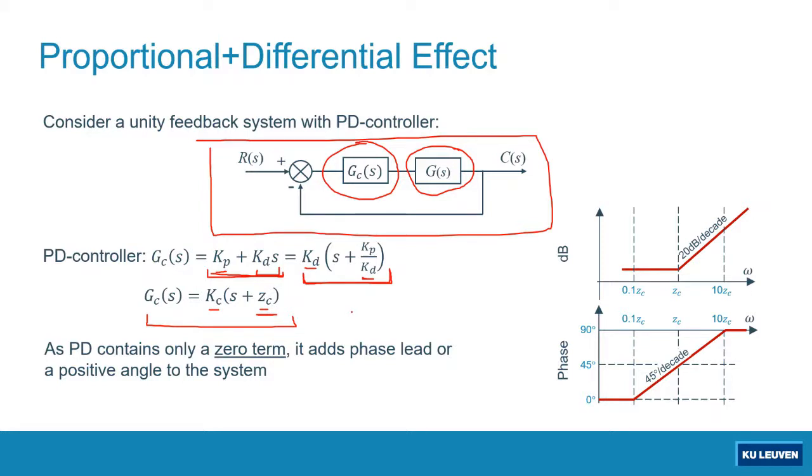If we are going to sketch the Bode diagram of this dynamic system, the dynamic system of a PD controller, you will see, using a straight line sketch, the Bode diagram will be like this, where the magnitude plot at low frequency will have zero slope, but at high frequency it will have an inclined magnitude plot with a slope of positive 20 dB per decade, right?